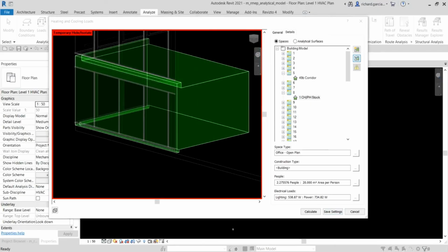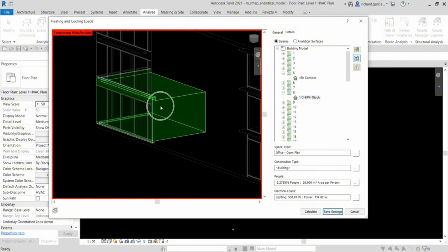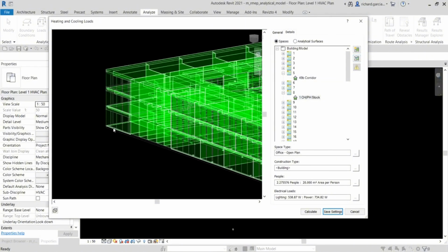As you can see, it's not that difficult. Of course, you need to use your view cube here to see it nicely. Now, to discontinue the isolation, you just need to click isolate again, and you will go back to the view. Let's say, for example, I expand zone 10 here. As you can see, I have a couple of spaces. If I want to highlight that zone, I just click the zone and then click highlight. There you go.